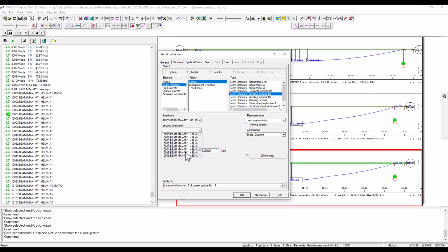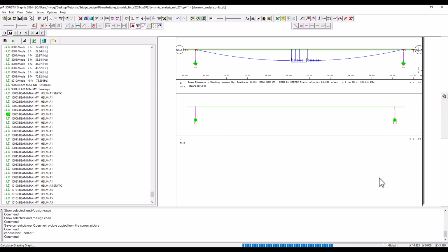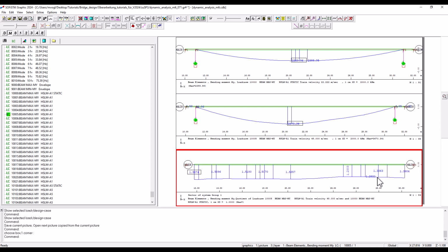Note that the maximum occurring static bending moment is 0 at the supports, while the maximum occurring dynamic results will be unequal to 0 due to inertia effects, leading to a high amplification factor. However, as the bending moment is anyhow small in these points, we can disregard them and focus, for example, on the span, where we have in this case a dynamic amplification of about 50%.